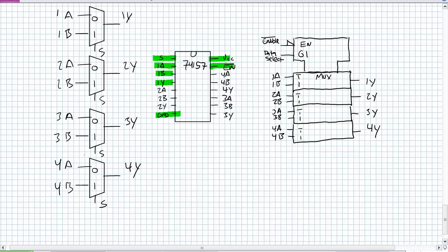And you can instantly see using this ANSI IEEE logic symbol, okay, I got 1, 2, 3, 4, 2 to 1 multiplexers. And by the way, there are pin numbers on this thing too, like that. It has a little parentheses 2, parentheses 3, all the way, so on and so forth, to match this thing. So in addition to the pin numbers, which you'd get from the pinout diagram, using this definition, you get to see how the thing works. So it's pretty cool. The ability to use the ANSI IEEE logic symbol kind of shortens your data sheet. The symbol itself is a data sheet.